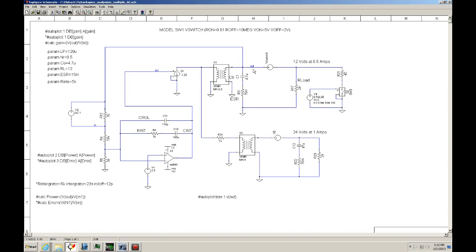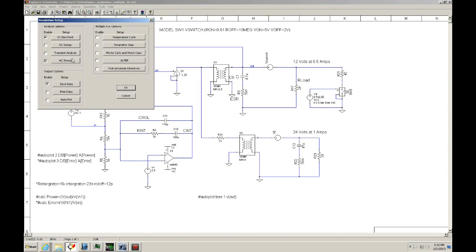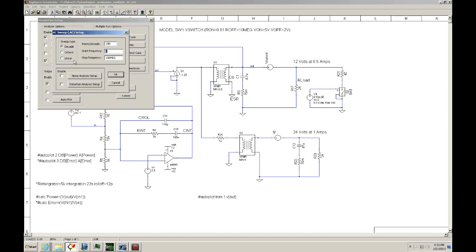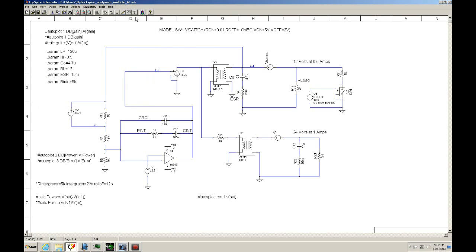So in this case, I'm going to have a total system loop response and then the response of the filter. And basically what I'm trying to get at is I want to see whether it matches with my calculations. Okay, so I'll go ahead and run the Bode plot from 1 to 100 meg, 100 points per decade. I'll go ahead and run.